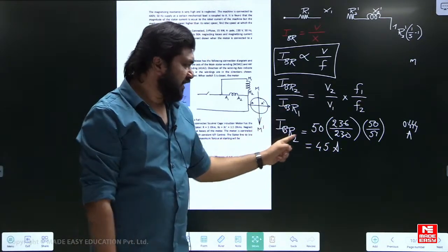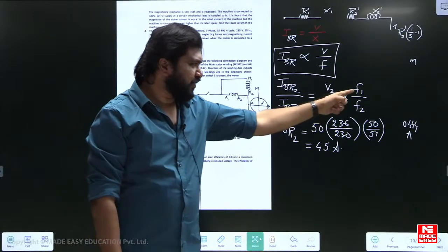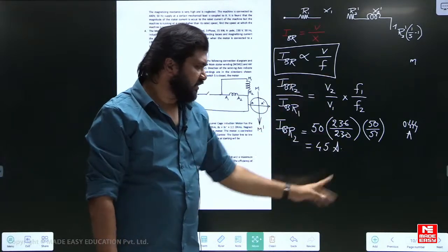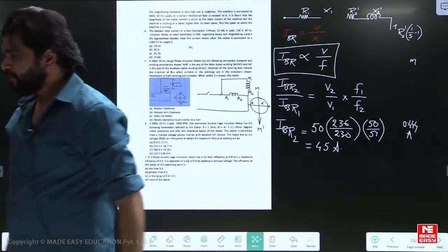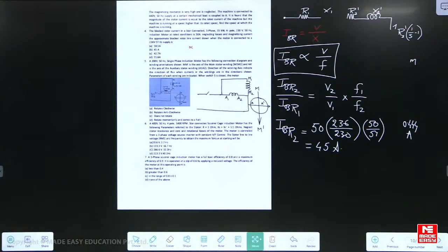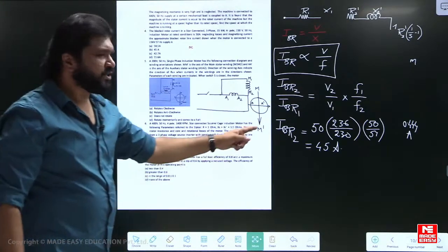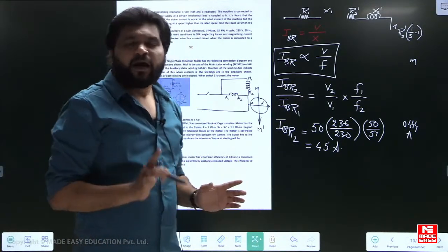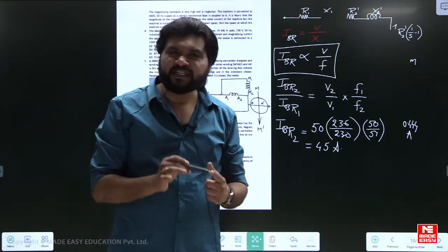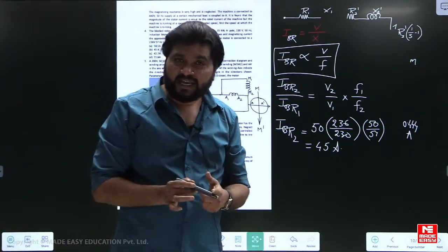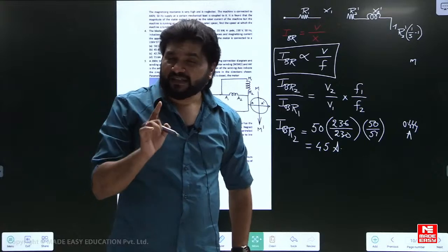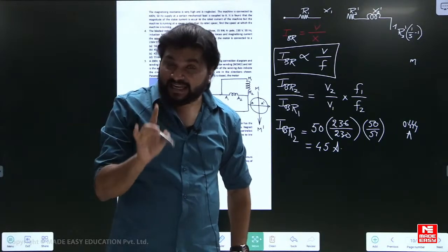First I_BR1 is 50, V1 is given, f1 is given. Next, V2, f2 are given. So what is I_BR2? Using this relation, you can solve the answer. 45 amperes we will get. This is question number 4. And question number 5, I just now explained to you. All you have to do is one thing: apply network theory basics. Find out the impedance angle of the auxiliary winding and the impedance angle of the main winding. Then, based on the impedance angle, the currents in the main winding and auxiliary winding will be lagging the voltage.